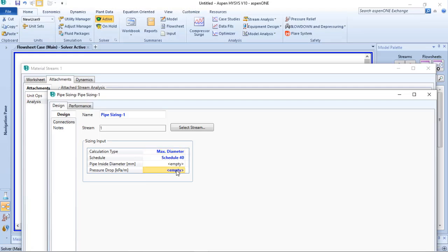And what I want is, according to item 1 of the pipe sizing hydraulics problem, the question is: what would be the pipe size ID required for an allowable pressure drop of less than 0.5 bar across the pipe, assuming you found a supplier who sells commercial pipe sizes as per ASME B31.3.